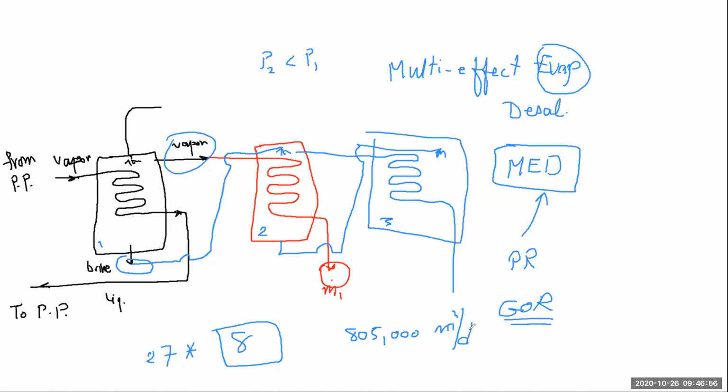Mechanical is not the best performance, because we still have a problem in the mechanical: the mechanical power needed for this unit is substantial, and therefore the energy requirements are higher. Accordingly, the market share is not too much. The units are initially not big. So far the mechanical vapor compression units are limited somehow to something like 5,000 cubic meters per day.